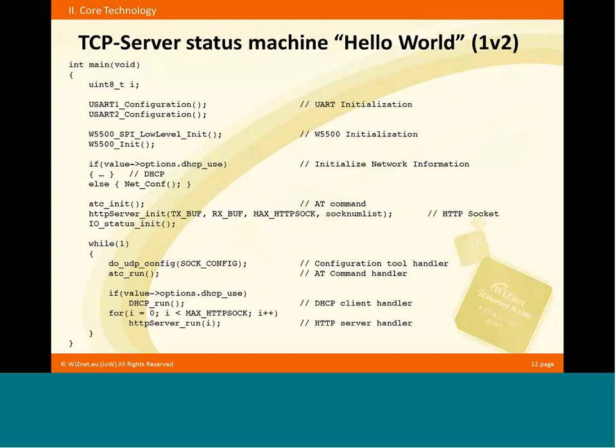Just from time to time, we go here into checking status, and if there is something to do, we go to the handler. If not, we come out here instantly. So this is not occupying the MCU. You have all the time to do any kind of real-time application. What is happening here?